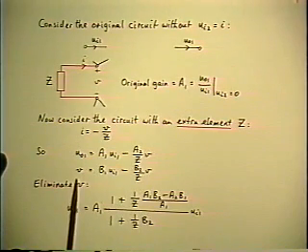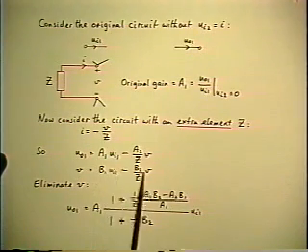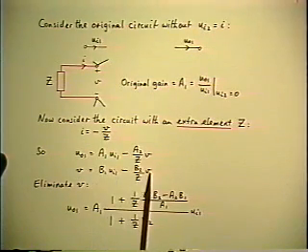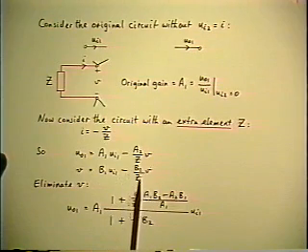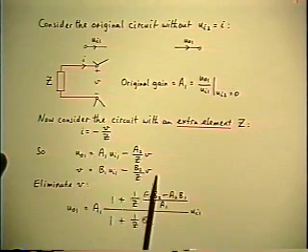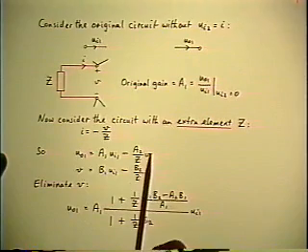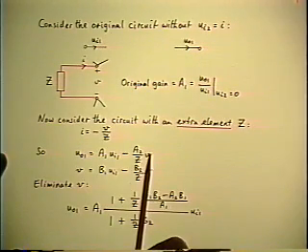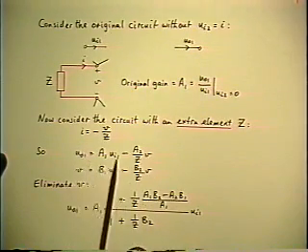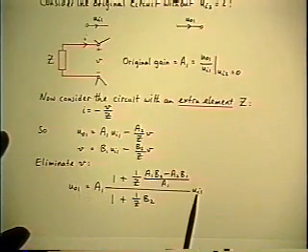And the second equation says output number 2 is B1 times input 1 plus B2 times input 2, which again is minus V over Z. And now you see you have V in 3 places. So you solve the second equation for V, substitute it into the first equation, and all you have left is output 1 and input 1. And when you solve it, you get this line.